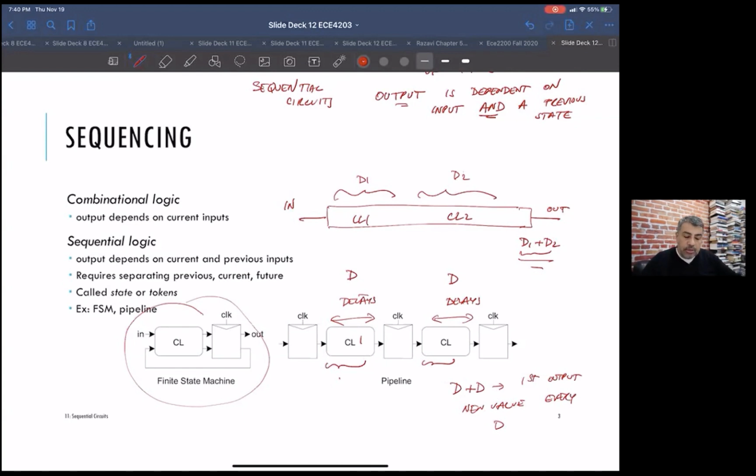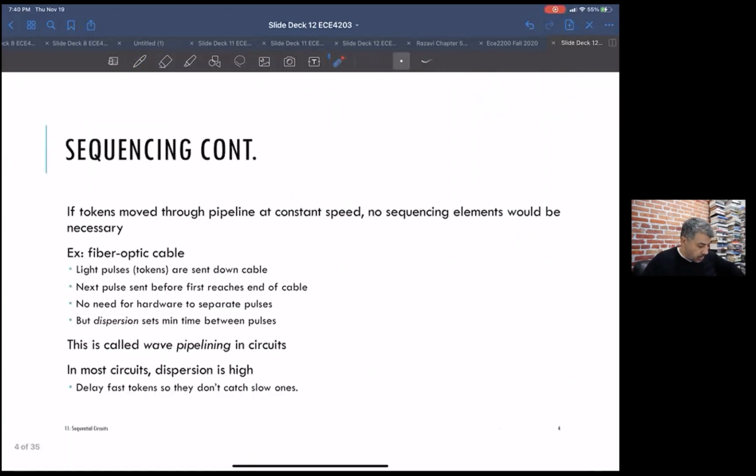And so a pipeline also has the same thing. It needs to be able to tell the difference between this guy and this guy. By putting these clock controlled stages, flip-flops or latches or whatever they are, you've basically separated this from this, and now you can pump stuff through this pipeline. Okay, and by the way, as an aside, this is a good time to talk about this.